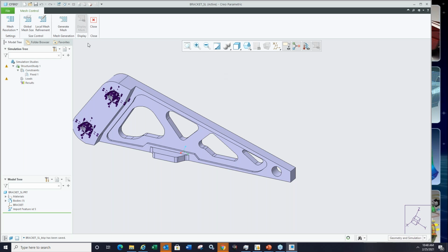And then now I just go and regenerate, you know, recreate the mesh, and it's going to essentially work on that process manager right in there. And you might see between that hole and that surface there, you're going to be seeing a higher mesh density since I changed it. So like this, if you're more of a seasoned FEA user, you're able to specify this. So that's the nice thing. I like how it has some basic capabilities for new users. At the same time, for somebody that may want a little more fine mesh refinement during the final validation stage, it's helpful, right?